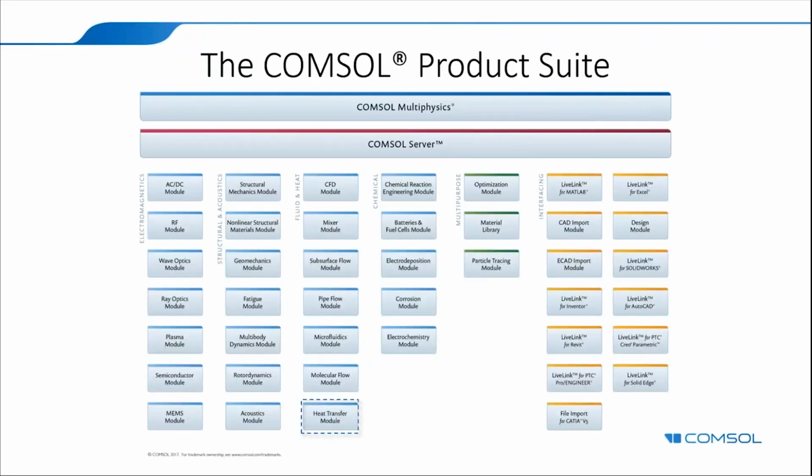Now, the COMSOL product suite is modular. You have the base COMSOL Multiphysics package that takes care of basic functionality in every physics area, and then the add-on modules to do anything specialized. For today's presentation, the relevant modules are primarily the Structural Mechanics Module that we need for thermal expansion simulation. If you're going to account for nonlinear material behavior, you might want to go with either the Nonlinear Structural Materials Module or the Geomechanics Module. Both of them basically contain a lot of inelastic nonlinear material behavior.